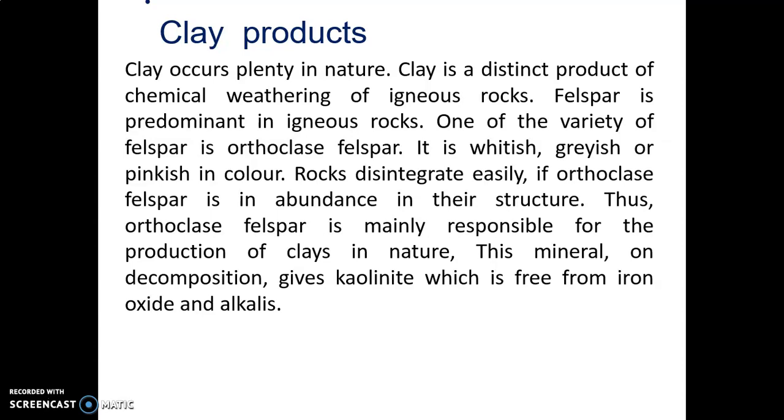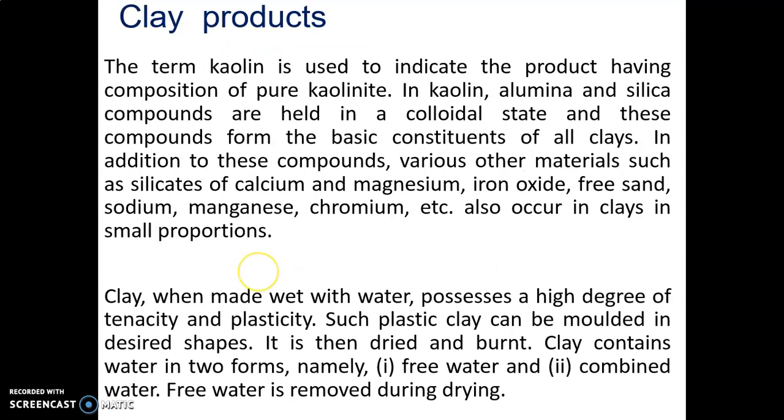This mineral on decomposition gives kaolinite, which is free from iron oxide and alkalis. The term kaolinite is used to indicate the product having composition of pure kaolinite. In kaolin, alumina and silica are compounds held in colloidal state, and these compounds form the basic constituent of all clays. In addition to these compounds, various other materials such as silicates of calcium and magnesium, iron oxide, free sand, sodium, magnesium, chromium, etc. also occur in clays in small proportions.